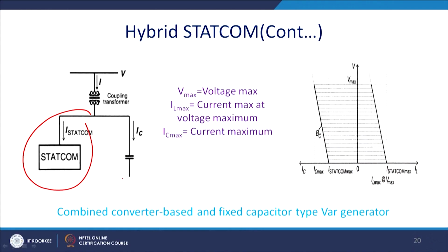So, essentially in most cases energy fed into the drives is inductive in nature. So, we require to feed capacitive VAR, and thus this kind of arrangement is getting attention as well as popularity. So, you see that this is a Statcom part and in parallel you connect a capacitor, maybe a mechanically switched capacitor, or a fixed capacitor or different kinds of HVC.